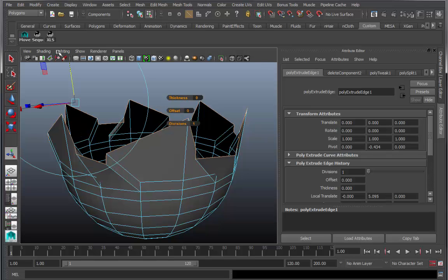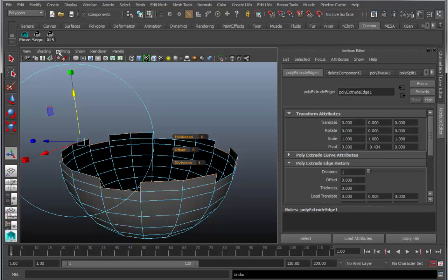So I'm going to press Z for undo. And I'm not going to click off. It's also vital right now to understand that by virtue of pressing the extrude button, we have already created new polygons all the way around this. So we need to simply pull them apart. They're created. Now we're just pulling them apart from the existing edges.